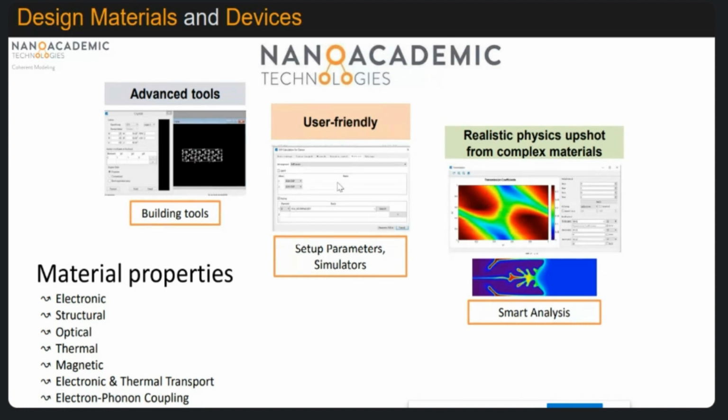The structure is modeled as you want to create it, whatever the desired shape of your structure, in our user interface. Once you have created the structure, you have to set your theory parameters, NEGF parameters, and some DFT parameters: pseudopotential, exchange correlation, K point sampling, basis sets, electron temperature, Hamiltonian, and spin related parameters, collinear and general spin effect. These can also be defined. And once you define them, you can run the calculation, and the simulation will be run by our tool, and you can visualize.